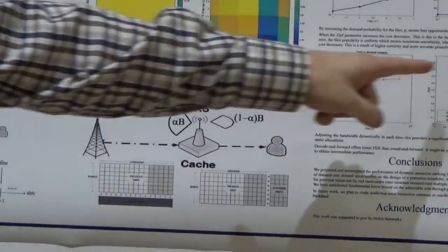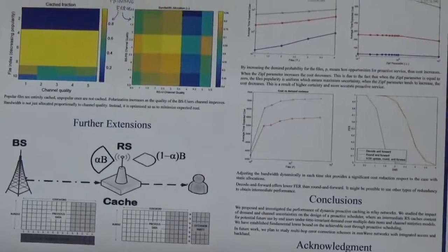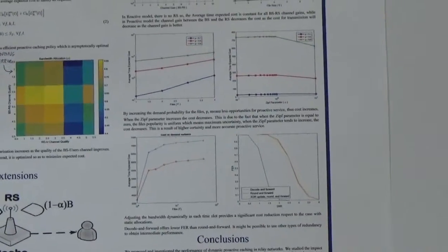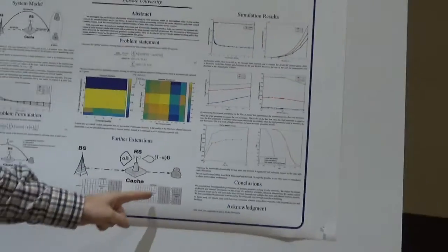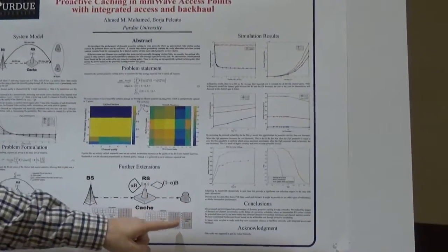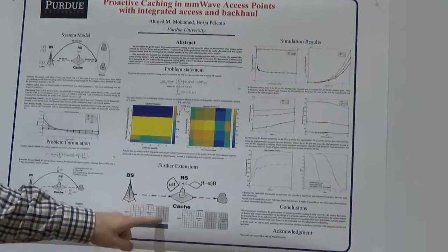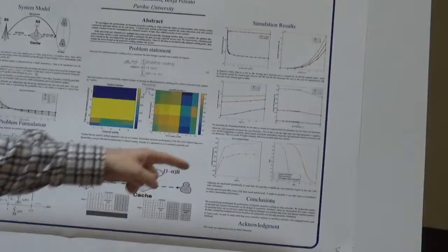Actually, in this plot that I show here, we're not just amplifying, we're rounding it, and then generating additional parity for those rounded values, and then forwarding everything, the original parity and the additional parity generated based on possibly erroneous values. And then the user would have to decode the first code to get the possibly erroneous values, whatever this guy received, and then decode the second code to recover the original information. That would be this other curve.